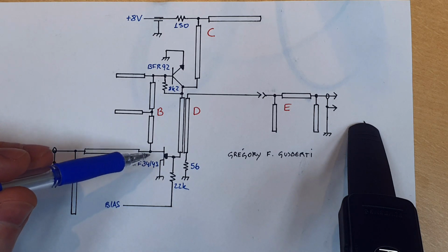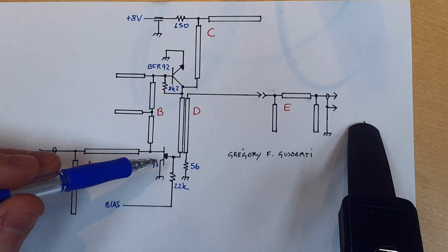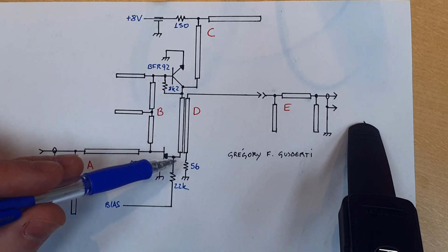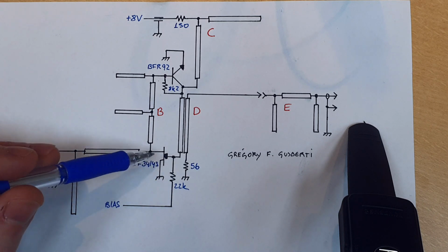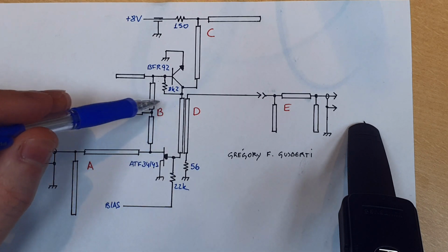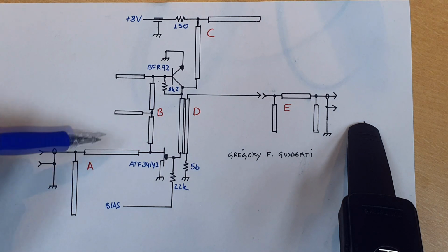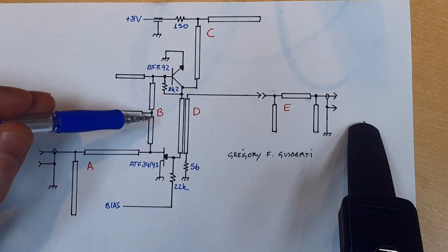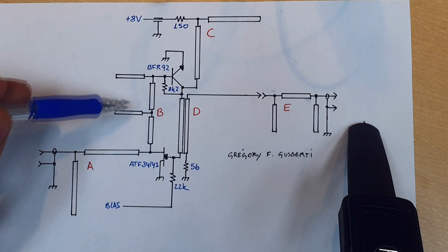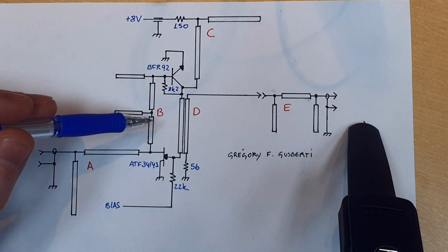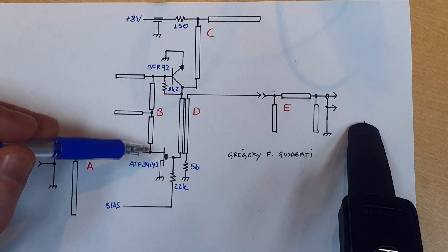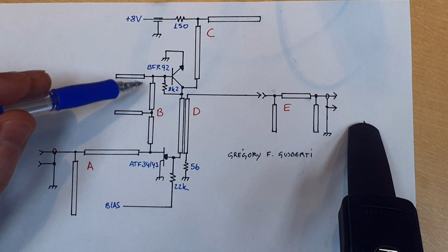So for the mixer, the 800 MHz path from the mixer to the input is an open circuit here. This transistor is a pseudomorphic high electron mobility transistor, and it is running in the circuit as a passive mixer, and you're gonna understand it later. The B network is made by two copies of this network here, but now the quarter wave is half because this network needs to work at 1.6 GHz to prevent that the 1.6 GHz that arrives here in the node of the mixer goes to the amplifier.